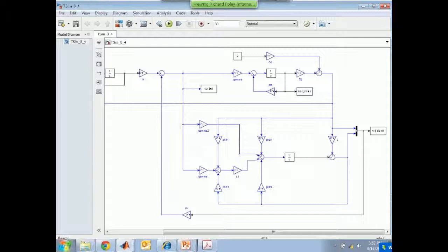And so what's coming back through this feedback gain matrix is the entire state vector down here. And I haven't actually bothered to simplify this, but if you can simplify it, you can get it to look a lot simpler than that. But this here is the x2 hat k minus 1 minus L times x1 of k plus 1. So we're adding in L times y of k plus 1 here to get the actual state vector that we need.